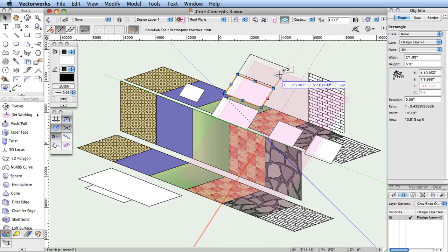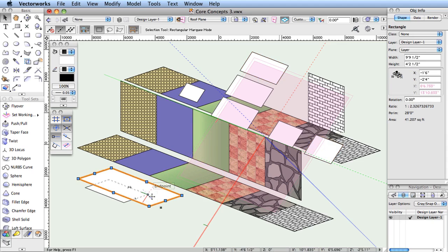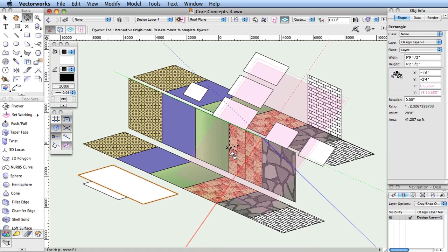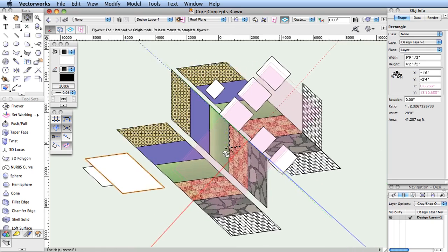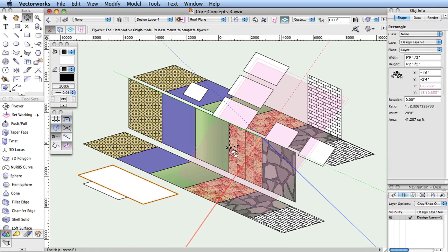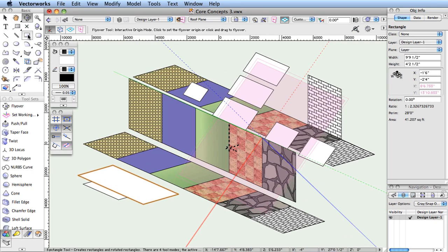Working in 3D requires a plane in space, so that clicking on the flat display can be calculated to intersect somewhere before infinity. All 3D tools and most planar tools can dynamically set working planes for the next drawing operation. This makes controlling the working plane very manageable. The screen plane is a legacy concept that continues to have narrowly defined uses, but is not used in everyday modeling workflow.